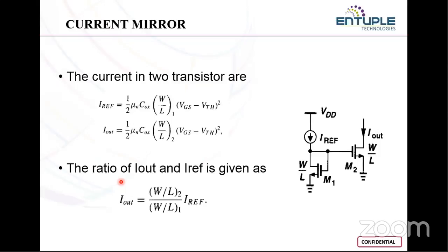So we have to change only the MOSFET width rather than length. Length should be matched for both the transistors. We can change width, but length will remain constant always.